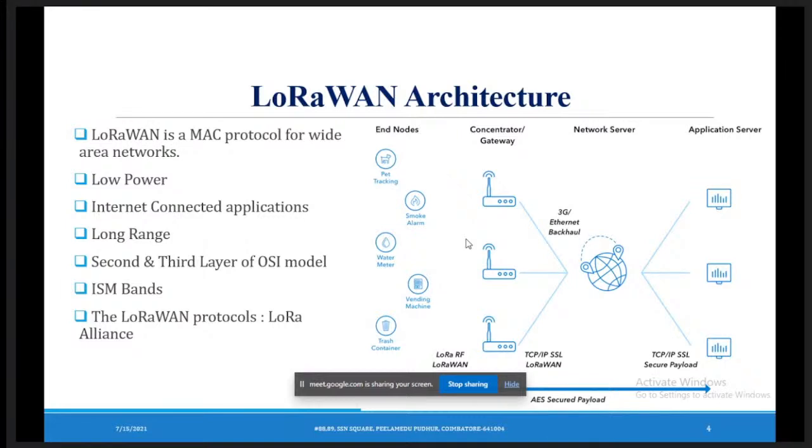After converting those data, I have to push the data towards the radio. So how can I convert those data packets into radio packets? With the help of an RFM95 chipset, I take the data and convert it into a radio packet. So the first one is a sensor and the next one is a microcontroller, an STM8 or an STM32 or an Arduino. Any microcontroller you can take.